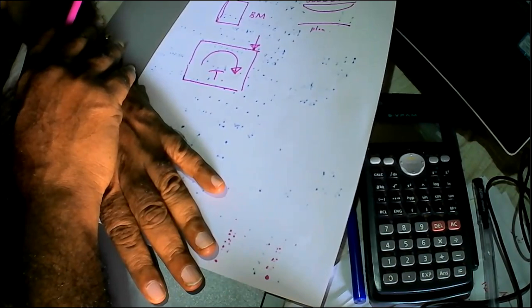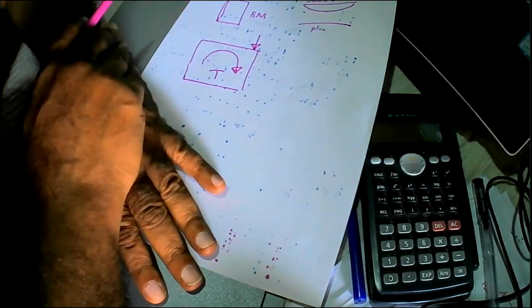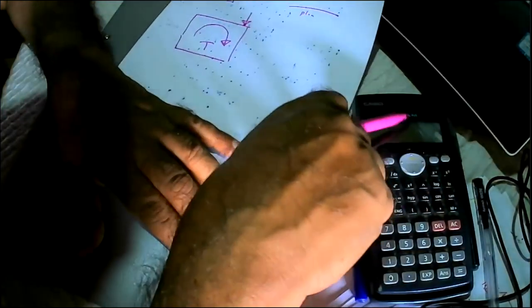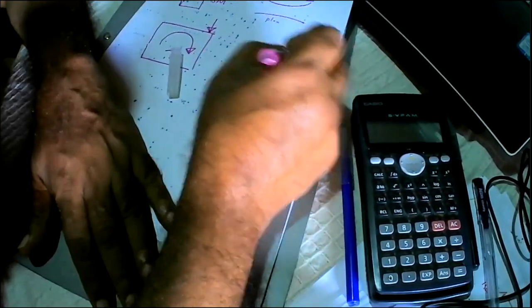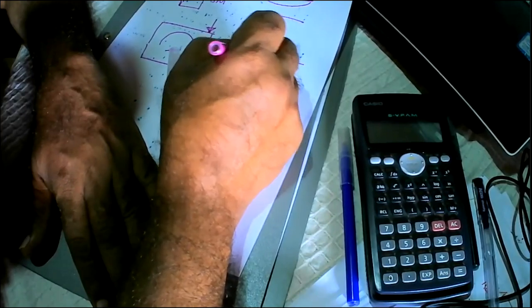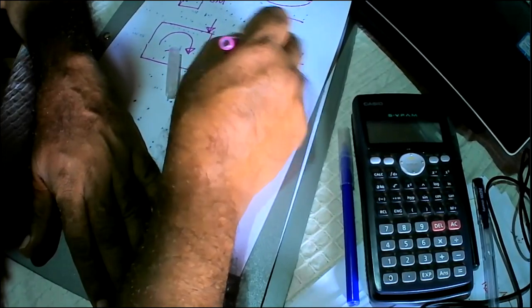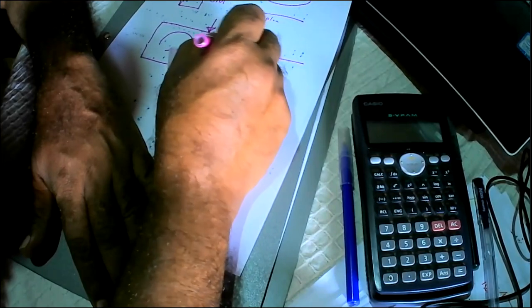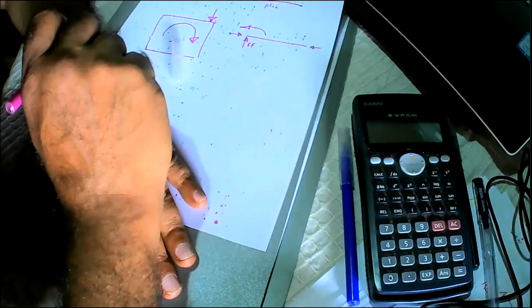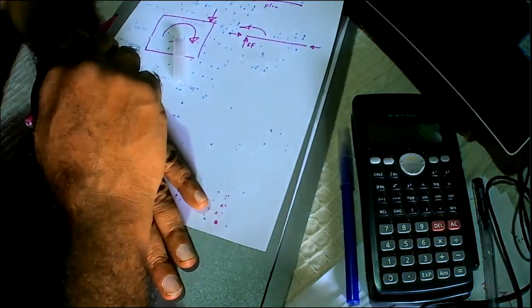But in normal situations, we consider beams to carry the vertical loads and deform vertically, so the important behavior that we have to capture is the bending of the beam, nothing else. Because when you are doing the three-dimensional analysis and you consider the beam element, you get 6 degrees of freedom. You get a shear force, moment, and axial force. And here also you get the same things. So you get 6 degrees of freedom.